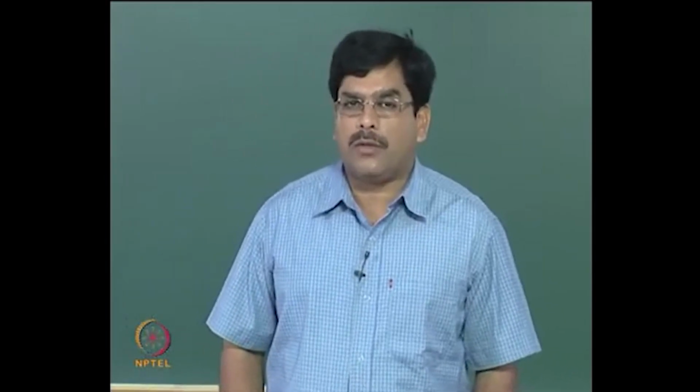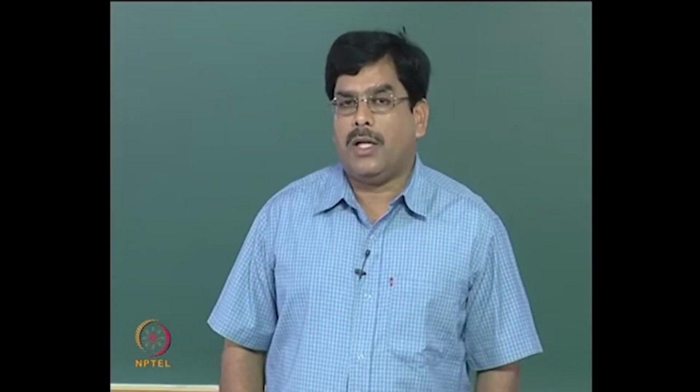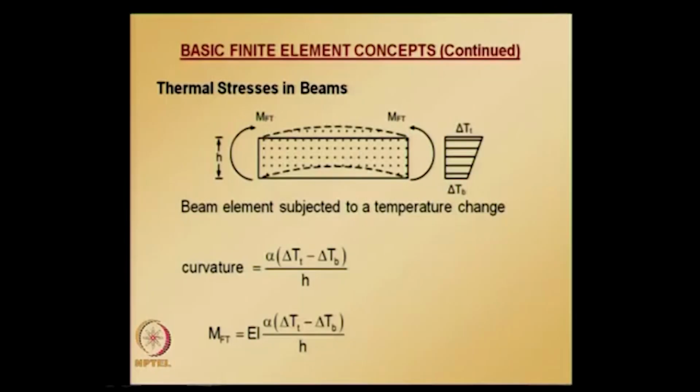And if you recall, what we did for uniformly distributed load is, for a beam span and the given loading conditions, find the fixed end solutions, and put them in a vector form following the sign conventions for applied loads, moments and degrees of freedom.